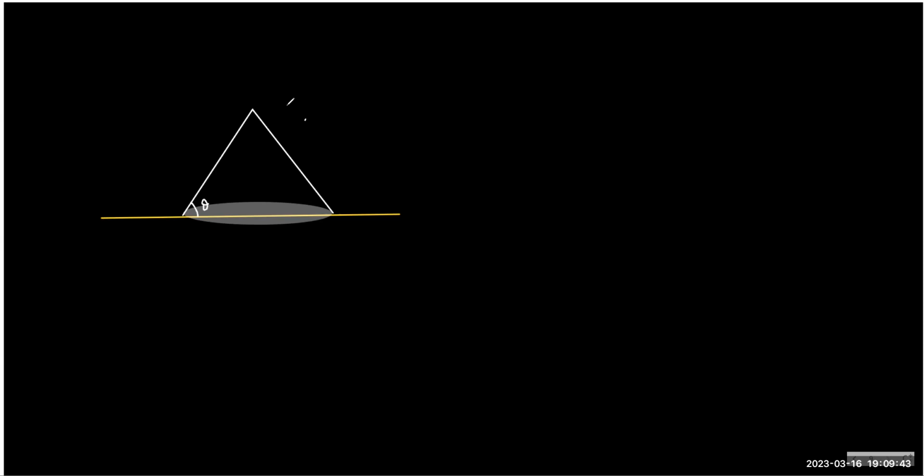Okay. Understood. So if you take it as very much identical, in fact, whatever you pour, it is always a conical shape, isn't it? So when you pour something, the H and R will always bear the ratio of mu s for the particle, right? This is like some particle. So tan theta is always mu s, which is H by R. In fact, H and R will have a finite relation.